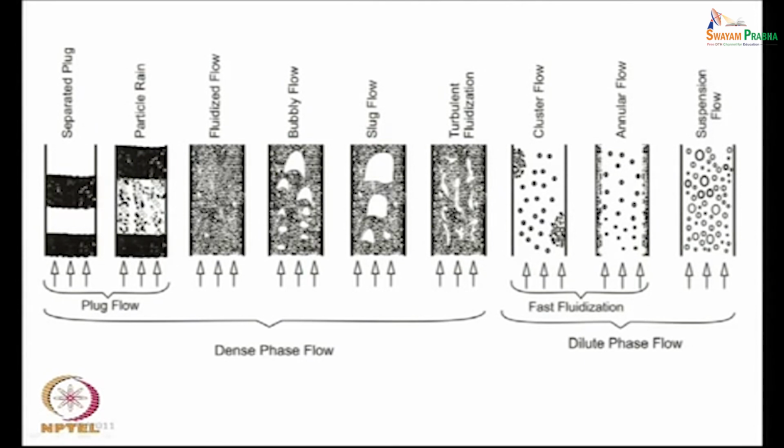Okay. So, when the dilute flow becomes non-slugging, we have the accumulated choking condition, and the condition when the dilute flow becomes slugging flow, from here we get a slugging flow, then it is called the classical choking. It is related to the formation of these gas slugs.